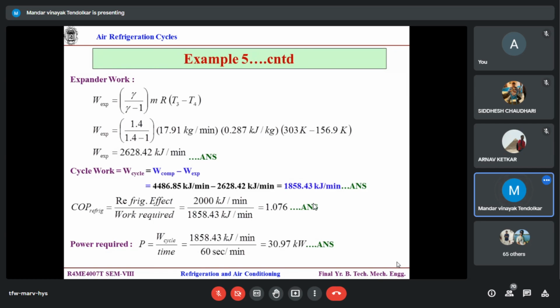When we study vapor compression system, COP would fall in the range of 4 to 6 or even 7, also, because it is anyways theoretical. And when we study vapor absorption refrigeration system, then the COP will fall even lesser than 1, maybe 0.7, 0.8, 0.9, something like that. This is a general thumb rule.